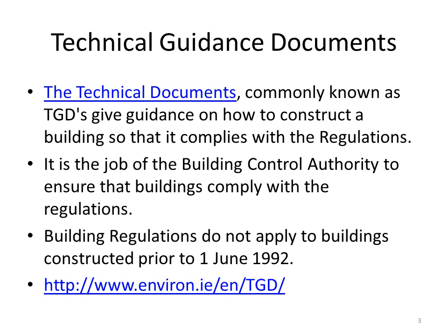Technical guidance documents, commonly known as the TGDs, give guidance on how to construct a building so that it complies with the building regulations. It is the job of the Building Control Authority to ensure the buildings comply with the regulations. Building regulations do not apply to buildings constructed prior to the 1st of June 1992, as the building regs in Ireland as we know today were only introduced at the beginning of the 1990s, and any buildings that were constructed prior to that, if anything, were built to the British standards.